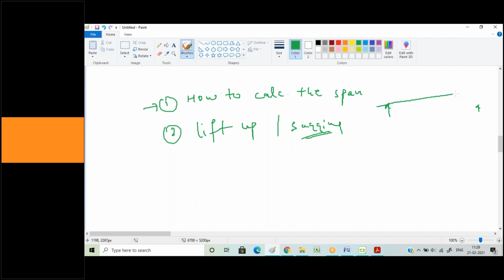Obviously, we all might be through with this term, what sagging means. Say this is my support and this is my line. What is actually happening is my line is behaving in some way of this sort. Again, it's a magnified view. Let's not take it to be that serious. So here, what my friend is saying is 2.5 mm. This has to be below 2.5 mm in order to say my supporting is correct. Yes, you're 100% correct. This has to be below 2.5.